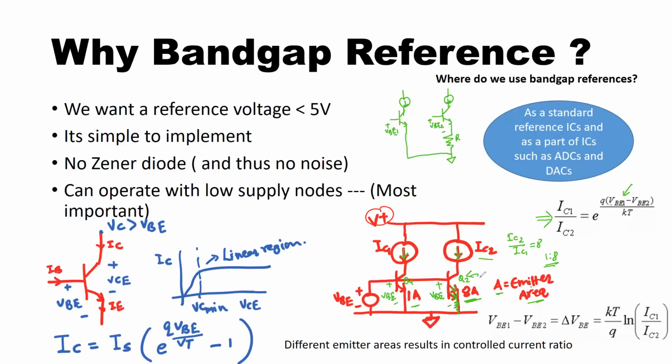because we use different emitter areas, right? So therefore, the voltage drop across the R is given as I times R here, or let's call it RE. RE will be VBE1 minus VBE2. Okay, so because of the larger current in transistor Q2, you will have a smaller VBE across its forward bias junction. Okay, and that's how you take advantage of this circuit, and you modify this circuit into this version. Rest remains the same.